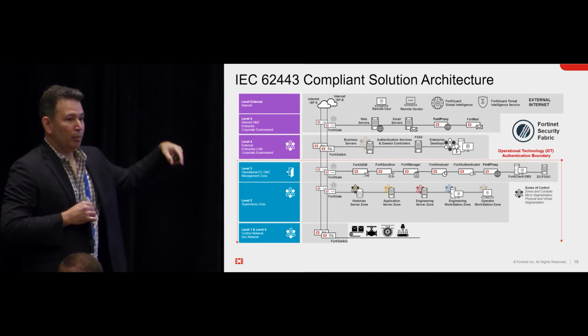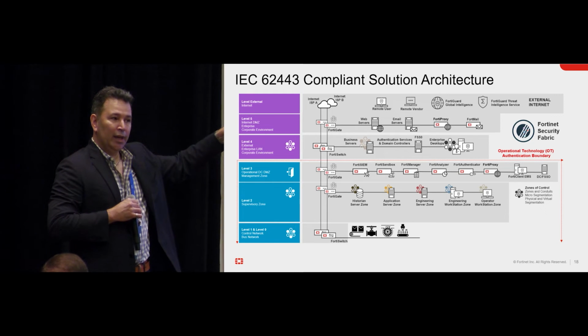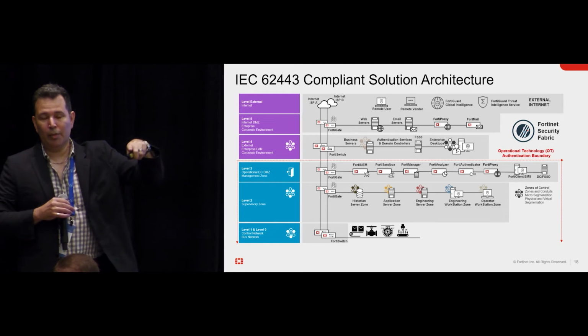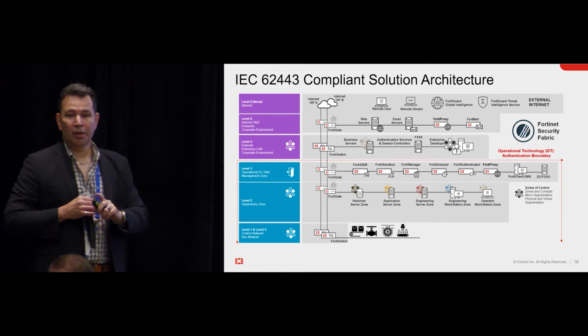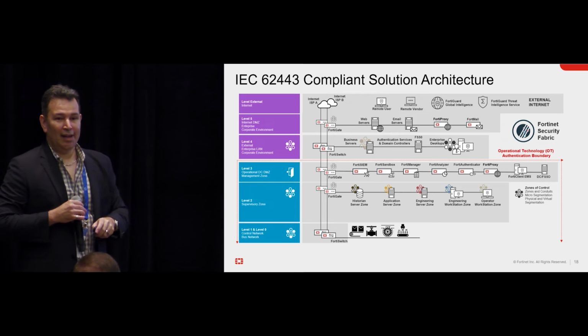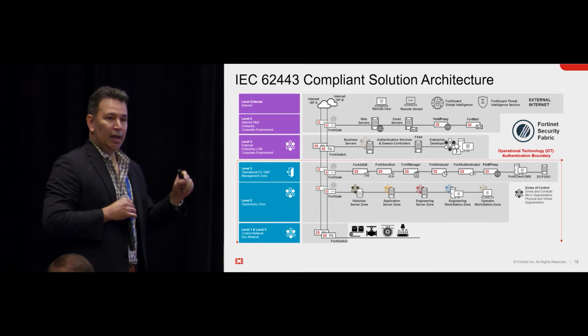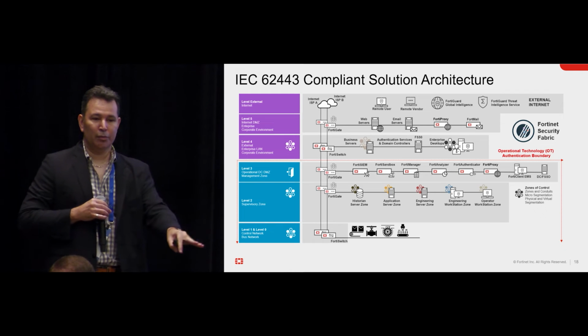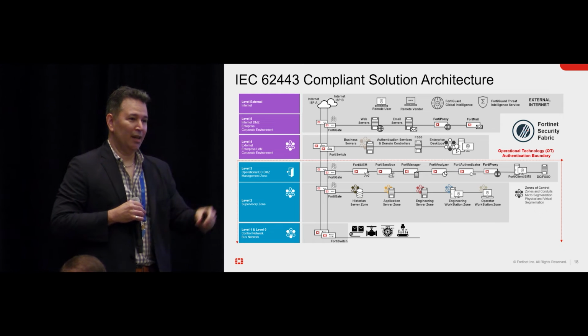But if we go back a couple of slides and look at that Modbus breakdown, now we're looking at layer 7 OSI, which will allow you to do microsegmentation based on application. And that's a really powerful tool. Because for all of us that have an engineering mind, that means I can create segmentation based on whatever comes, or define it by software, or as they call it, software defined, right?